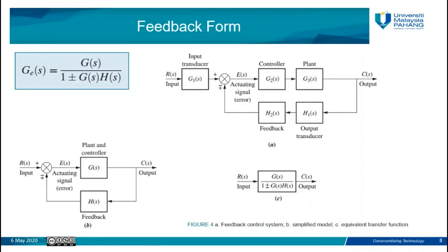The third topology here, which we already saw in chapter 1 when we talked about the closed loop transfer function, or feedback transfer, closed loop control system or feedback control system, we call the feedback form. This system consists of two subsystems after the summing junction, G2 and G3. These two are cascade because they are connected in series. And we have feedback going through H1 and H2, which are also cascade in this case.